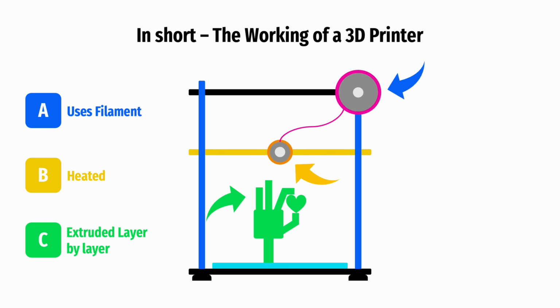Now, what are its advantages and disadvantages? Its favorable traits include easy printability, low warping, and food-safe properties. However, PLA is avoided by some prototypers due to its brittleness and limited heat and UV resistance. These mechanical limitations can be a drawback in applications requiring higher durability and resilience. Even with these drawbacks, PLA is still the most popular plastic and has the most compatibility with 3D printers across the world.